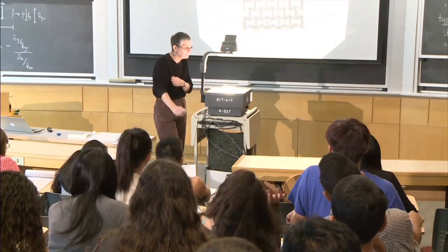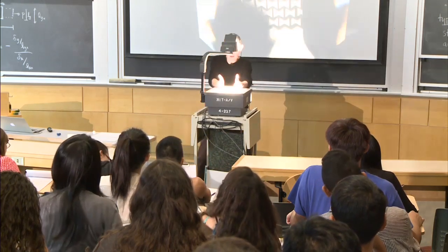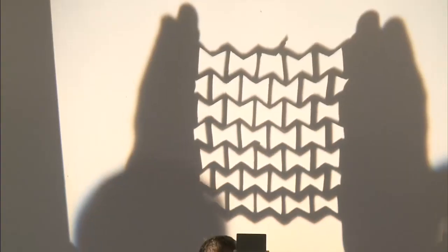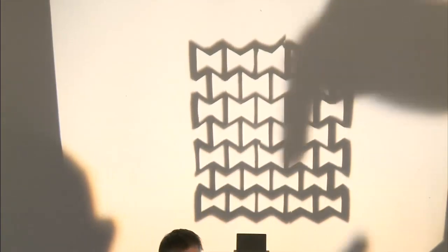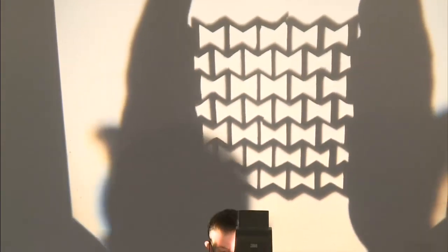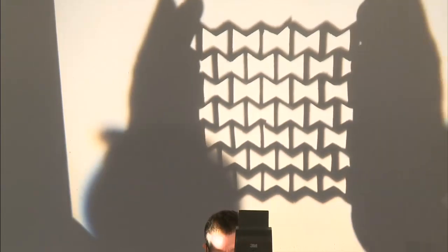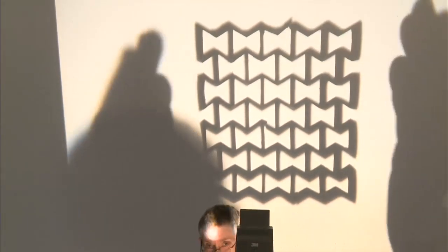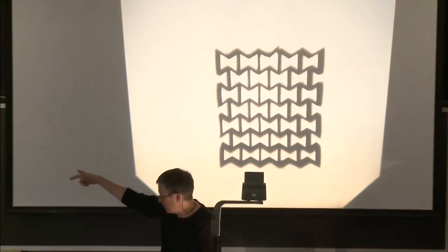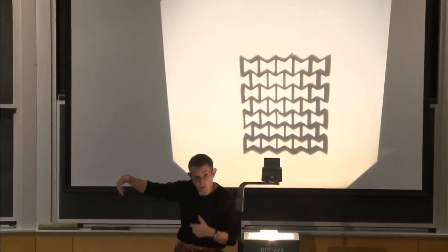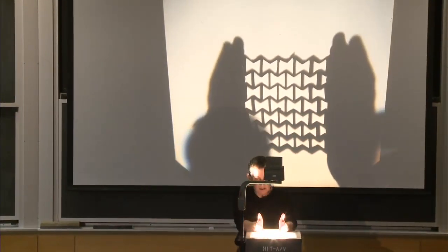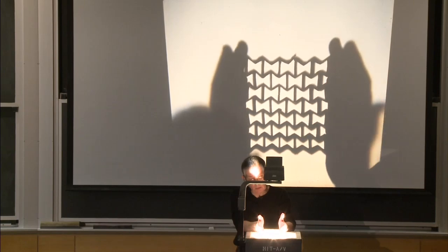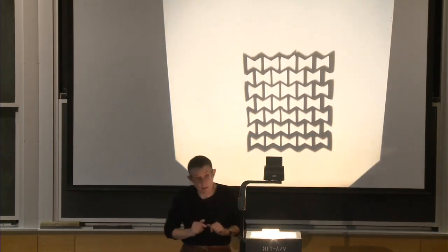Yeah, that's good enough. Okay, so if I take this and I squeeze it like this, can you see how I'm pushing this way, but it's also contracting that way? So the fact that this strain, let's say that's the x direction, and that strain in, say, the y direction, they're of the same sign because I've got the negative in the Poisson's ratio, it's going to have a negative value. So that's something that's very unusual, and it's the particular arrangement of the cells in this honeycomb that gives you that. So that's kind of an interesting little thing.